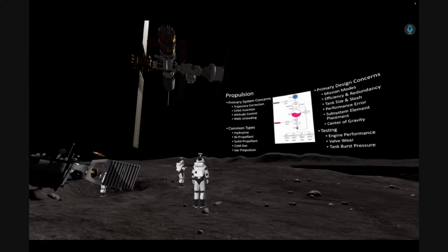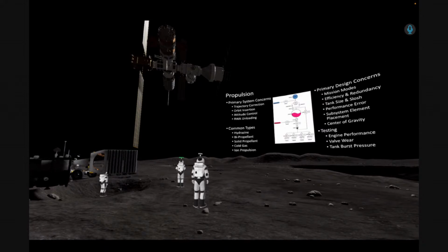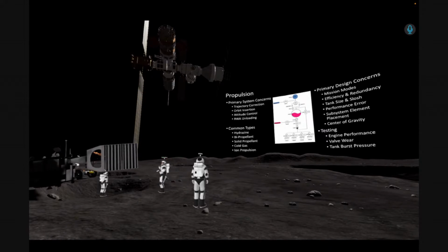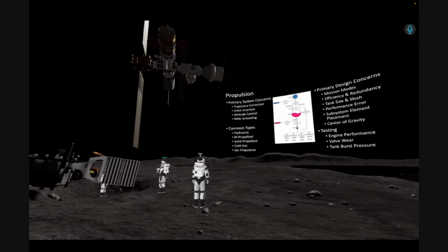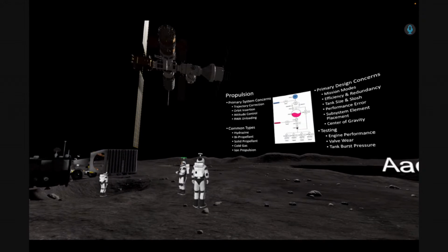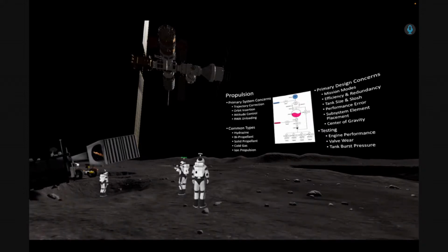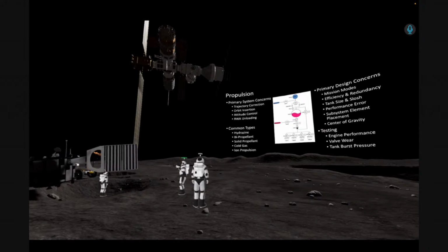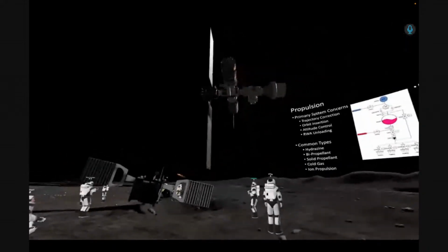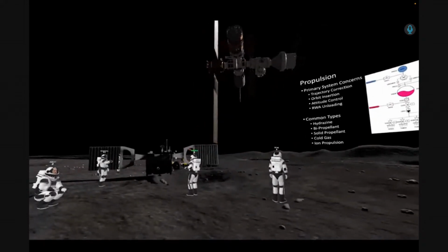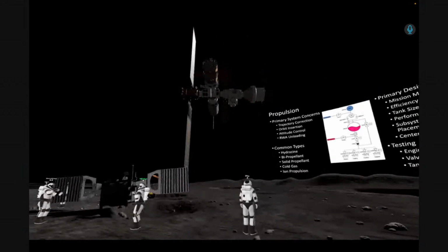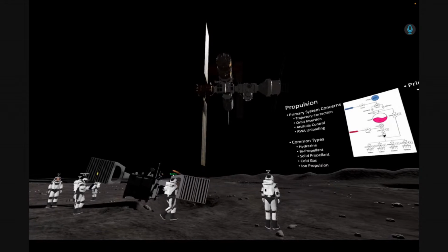Okay, propulsion. This is an amazing topic as well. So the idea about having propulsion is either to correct the attitude of the satellite. If you recall, the attitude is where my satellite is pointing to. So maybe we need to change that. For example, if I have a little rocket in here and I'm in space, I can actually move like this, or I can move to another side. That's super important if you have a camera in your satellite, and you need to point to a certain place. So you need to have propulsion for attitude correction. That's attitude control.